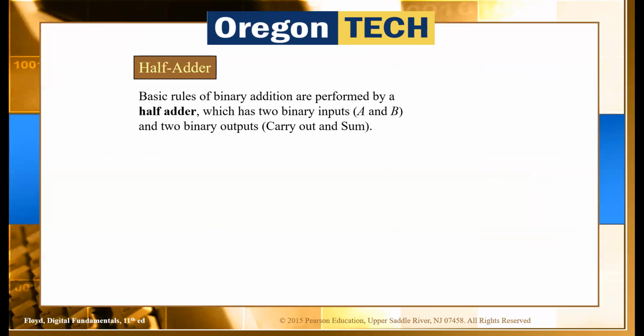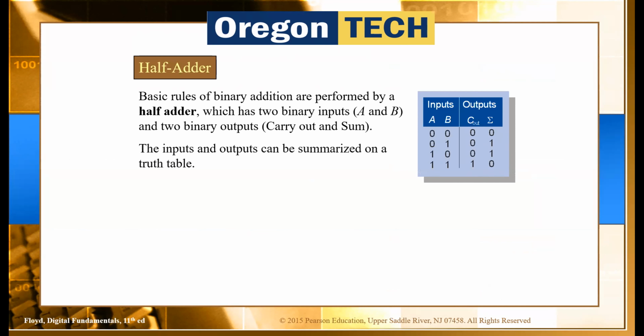Of course, we are adding in binary. We are adding two binary numbers, A and B, and we are supposing that we have only one digit for A and one digit for B. And this is the truth table of the adder. We have A and B, those will be my input. What about the output? This is the summation and a carry. A carry if the number exceeds the limit of my summation.